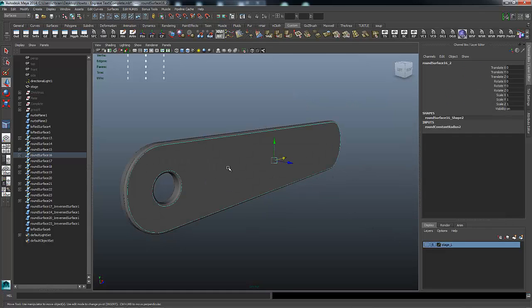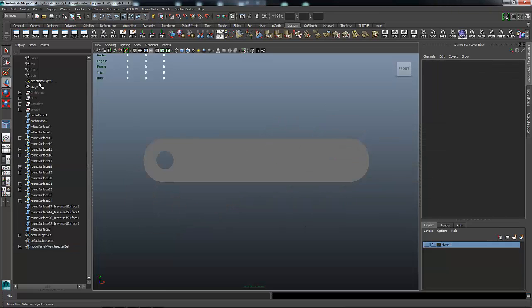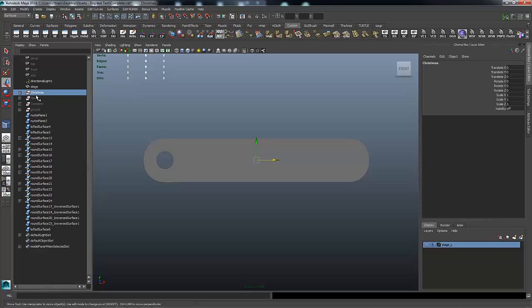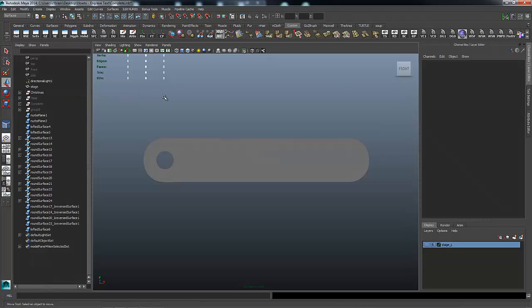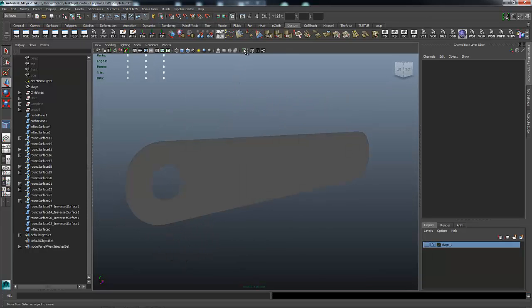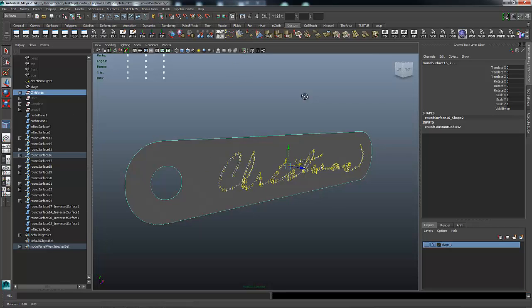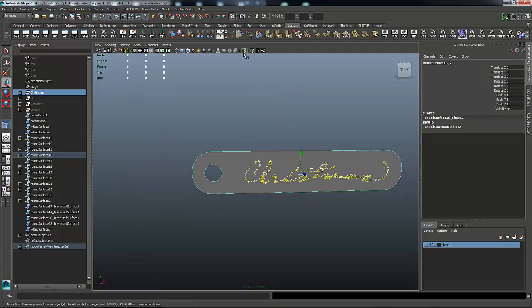What we need to do for that, we've already got the letters engraved, we just need to cut a hole for where the letters are going to go. So we're going to take this face right here, and we're going to isolate it. And then we're going to go to the front view. We're going to turn the font back on, Shift H, perspective. Oh, I've isolated, so that's why I couldn't see it. So we'll take that and this face, and we'll isolate the two, so it doesn't disappear when we're done. We'll auto-load the new object.